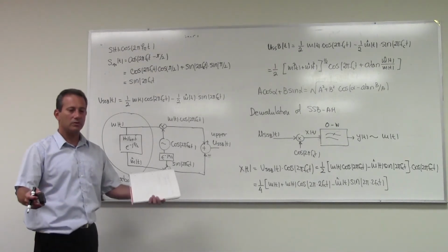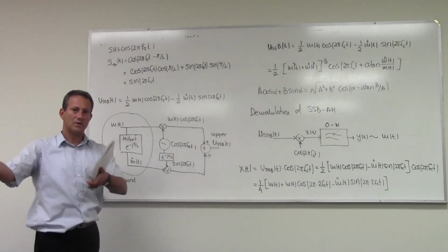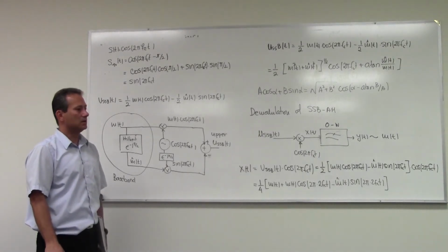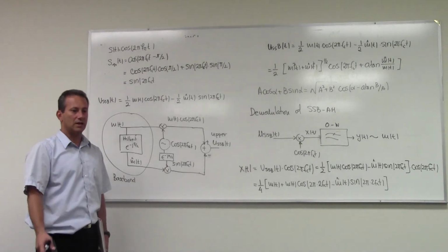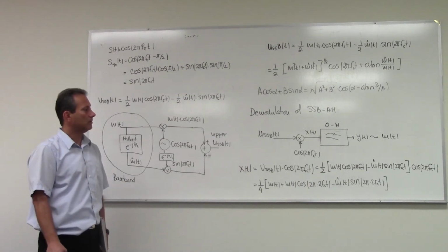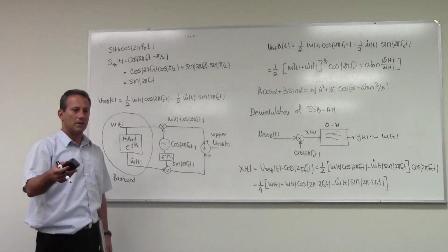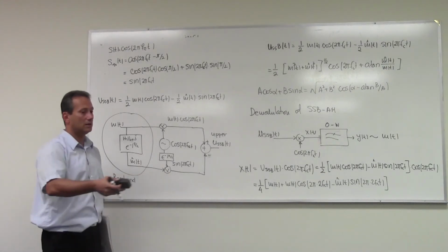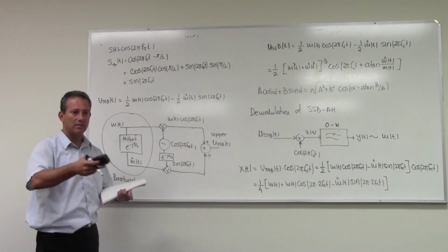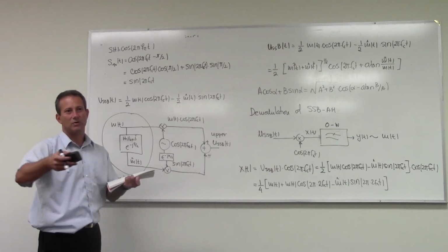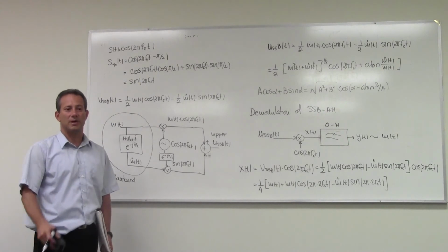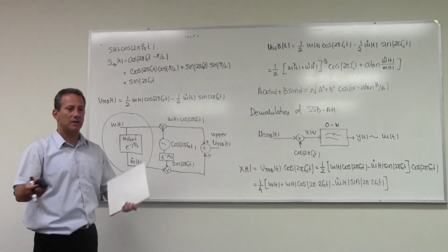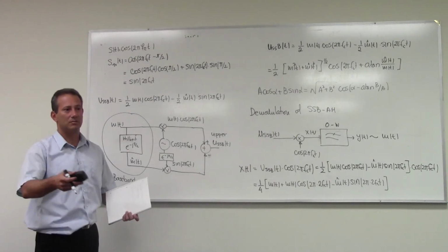So one motive why we do modulation is to be able to move our signal around and use whatever frequency band we desire. But the other one is to be able to share the same frequency band between multiple signals. If you have multiple voice transmissions, all the voice transmissions are generated in the baseband. And if you want to use the same line to transmit all of them, you have to stack them up, at least in a frequency domain, so that they don't interfere with each other. And that's the origin of the simplest multiplexing scheme, which is called frequency division multiplexing.